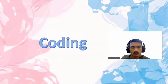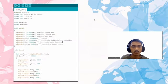So I'm going to be continuing presenting on the coding. Moving on to the first slide, this is the coding of our project of a reverse parking. As you can see, for the first line, I'm defining the CTS pin on digital PWM number 8. Then I'm putting the constant int for the piezo, which is for the buzzer, on digital PWM pin number 6.